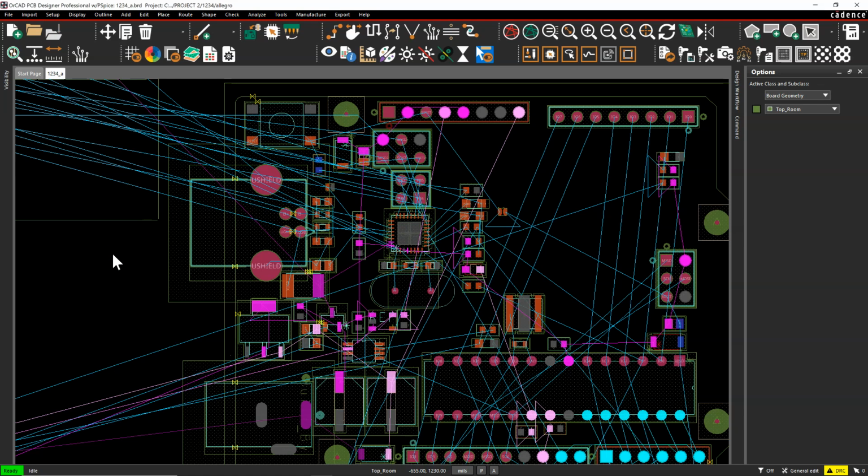And while that took some time to set up, the DFA or Design for Assembly spacing rules help us do Design for Assembly in real time and not after the fact. IPC guidelines for spacing are very helpful because it minimizes potential assembly defects often caused by otherwise poor placement and spacing errors. Applying the IPC guidelines manually would be very challenging, so it's very convenient that OrCAD helps us do this automatically with Design for Assembly rules.